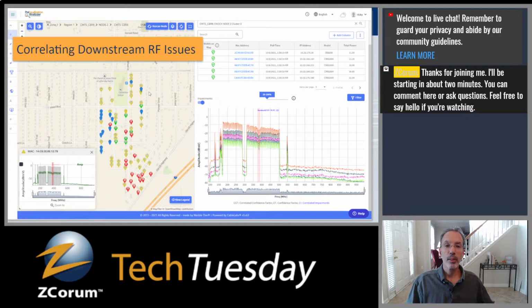So that's something else. Again, proactively, you can look at this and go, okay, I haven't had any calls from these customers, but I see the suck out, and that can be causing some issues for them. So I'm going to go ahead and see if I can address that. And you do the same thing. You can just click and try to find where the signal gets better. It might be this one, it might be this one. You're just going to find where the suck out goes away, and then it gives you an opportunity to look at where that cause might be.